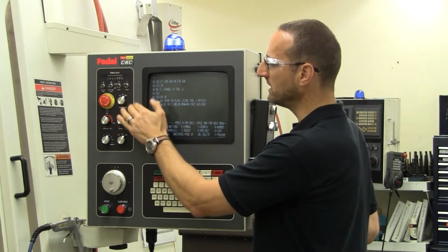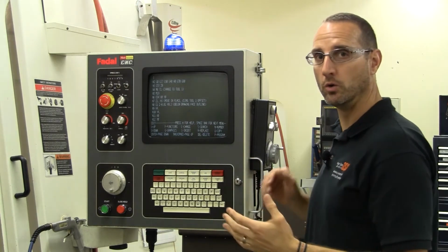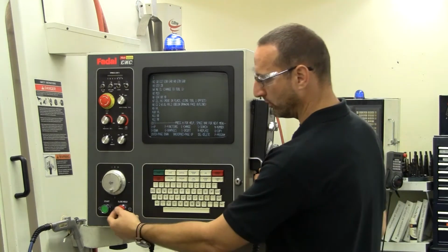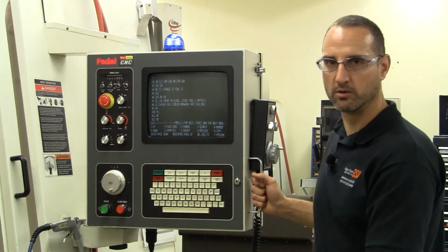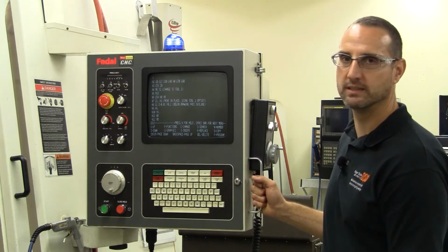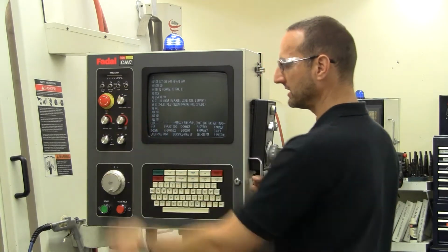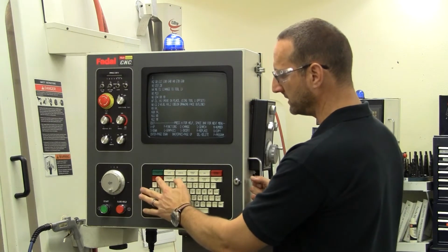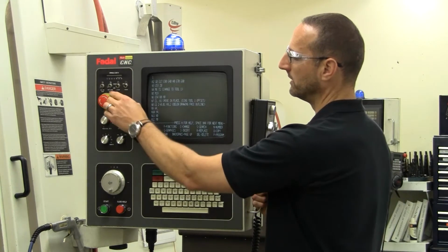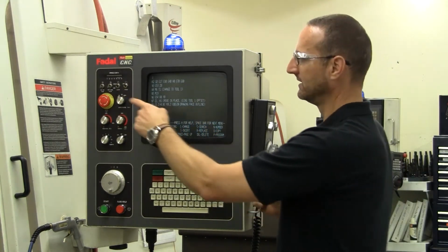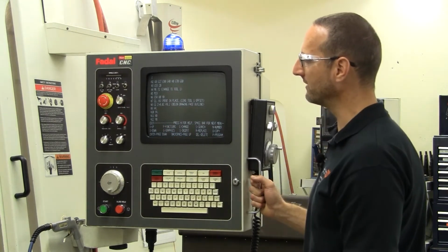Essentially, this selection is going to reduce the amount of reaction time that you as an operator will have to push the slide hold button to stop it if the machine starts going in a direction or doing something unanticipated that you don't want it to do. So you want to give yourself as much time as possible to react, to hit your slide hold buttons either here or here in order to pause the machine. I'm going to highly recommend, and require, that students start out at 25% of rapid travel.